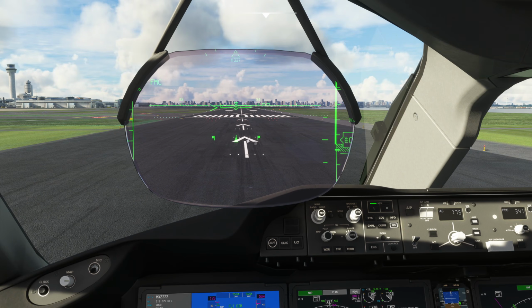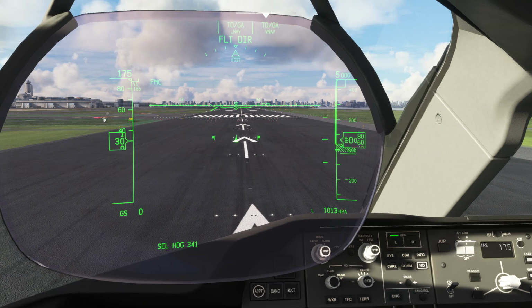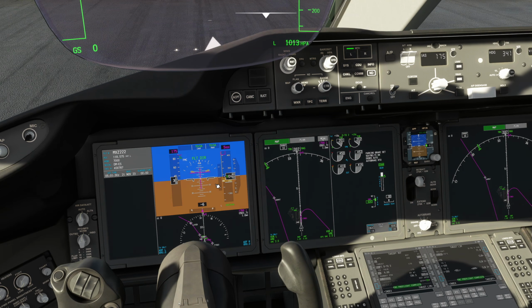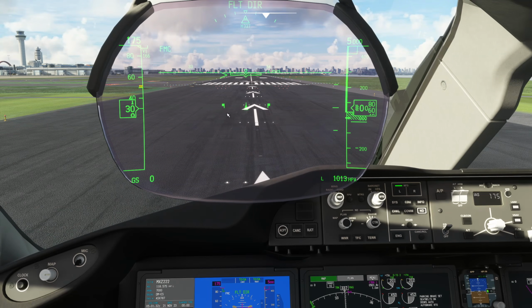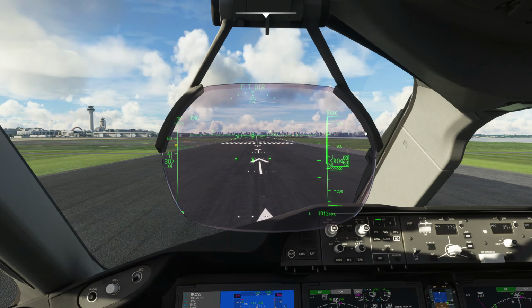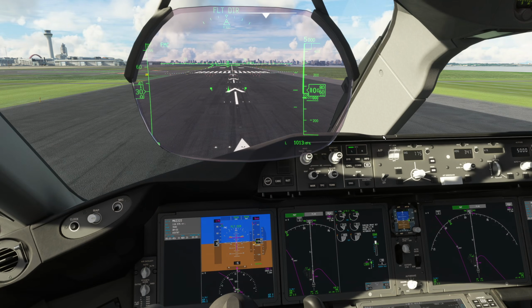We can see rotate, though. It will be visible in both of our HUDs, and it's visible on the PFD. Then we'll rotate the aircraft, and looking out through the HUD is the easiest way. We're going to move our airplane symbol up to the dashed line, the TOGA or takeoff reference line that we'll be able to see. Just bring that power back. Then we're going to get the positive rate call and ask for the gear up, and then we'll climb away.